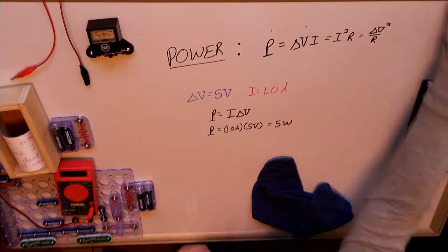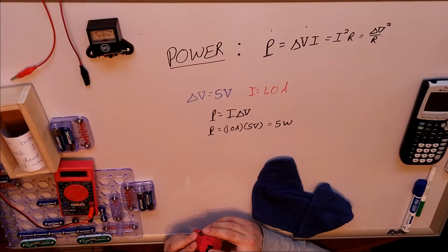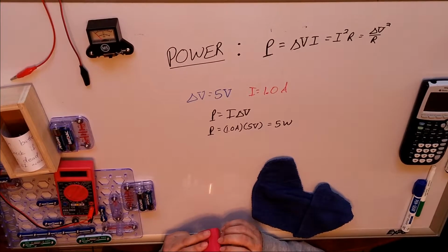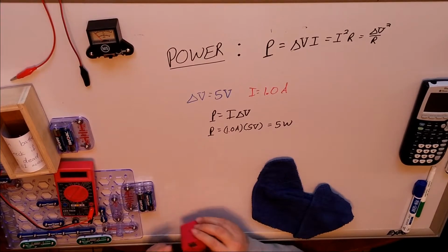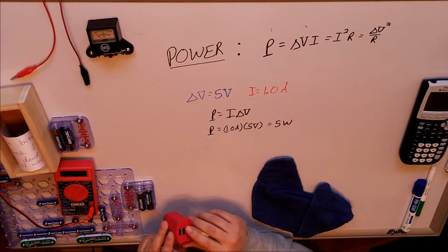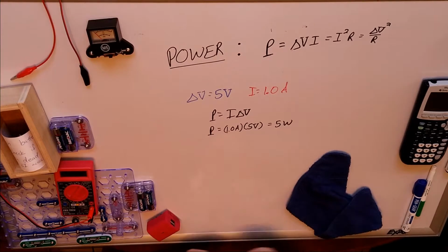Great. How is that different? Well, here's another one. This one belongs to a friend of mine. And it actually has 2 ports. One says 1 amp and the other says 2.1 amp. So let's take a look at that. It says that its output is 5 volts at either 1 amp or 2.1 amp. Well, we already know the first one, the one that's marked 1 amp, is a 5-watt charger. Many of the chargers that you have are probably going to be standard as that.